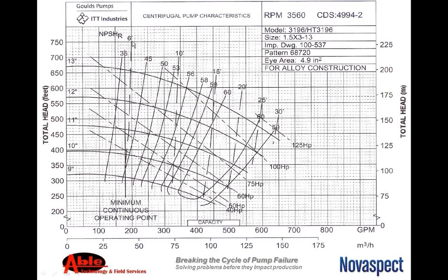On the upper, total upper, it's going to be your net positive suction head required. And that'll be in feet also. And then right below that, these are your best efficiency points. And you're looking at 60% is your best efficiency on this pump curve. You also will, further down, have your flow. It's going to be 0.